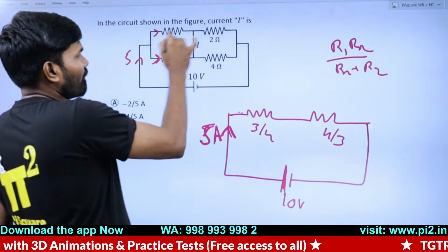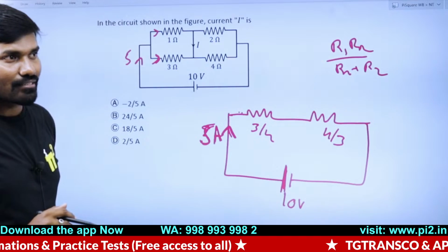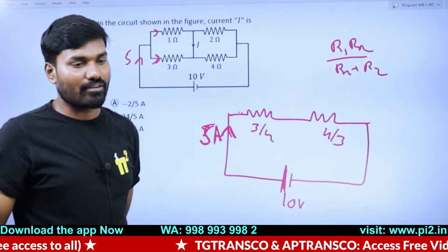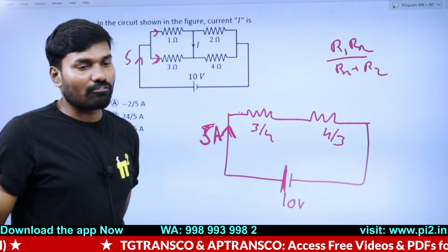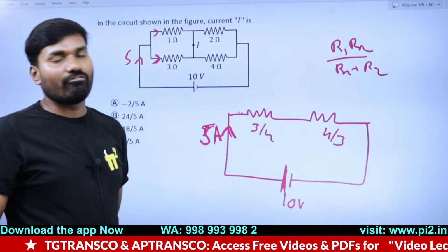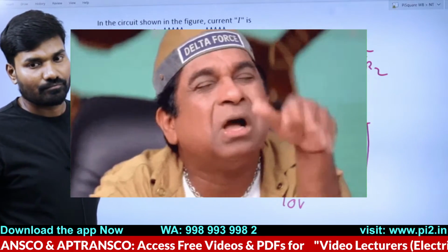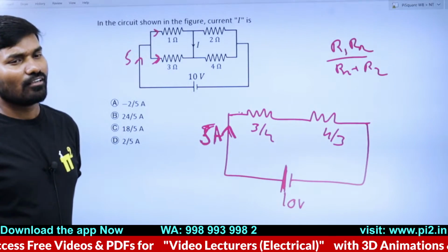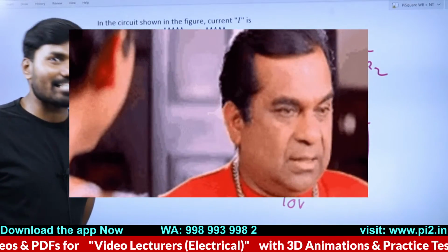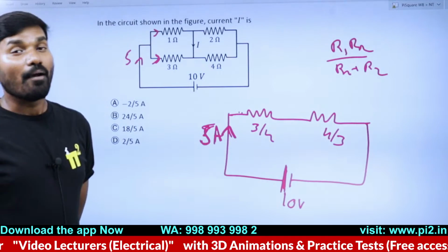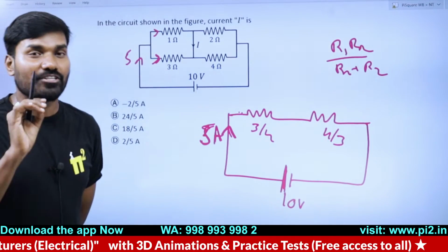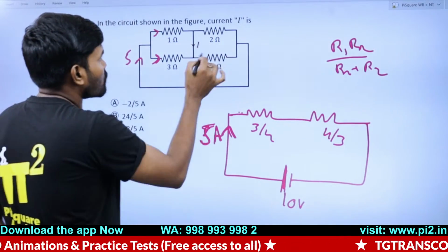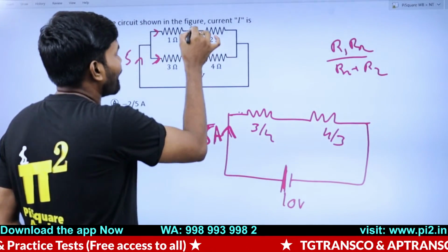Obviously, whenever you see this, the first thing you should think is, is this a Wheatstone bridge? That's the first thing you should do. Are you confused? Is it looking like a Wheatstone bridge? Yes, it is a Wheatstone bridge. Don't get confused, but the bridge is not balanced. Look at this: in these two arms bridging, you are not having any element. Rather, it's a short circuit.